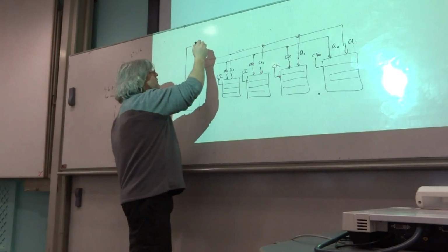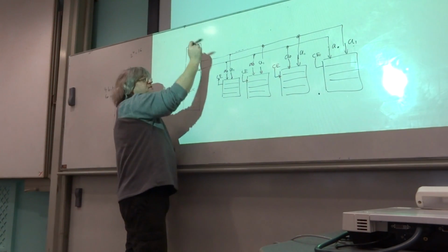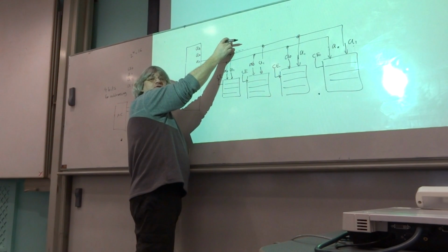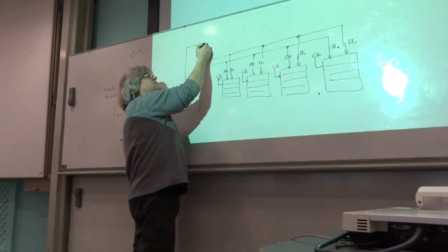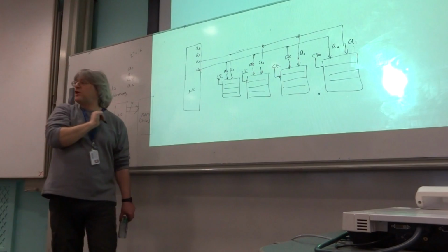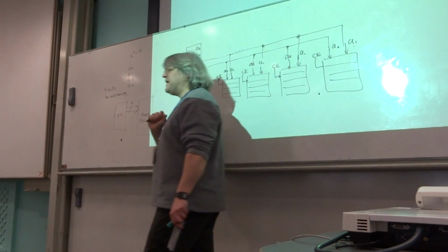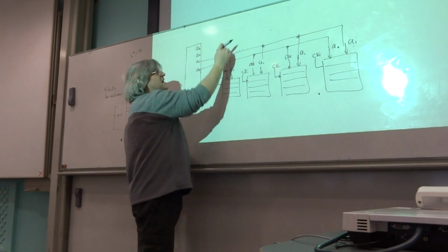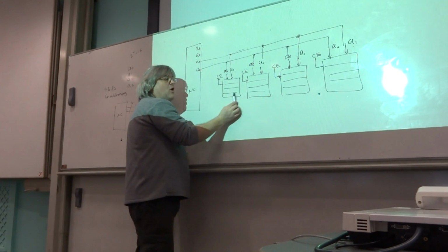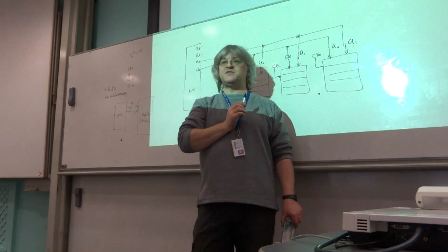Okay? Now, I've only got two here, so I'm going to have a little bit of combinational logic, but with two things here, there are four combinations, which is good, because I've got four devices. So for each combination, I would have an arrangement of logic gates, so only one of these at a time would ever be switched on.